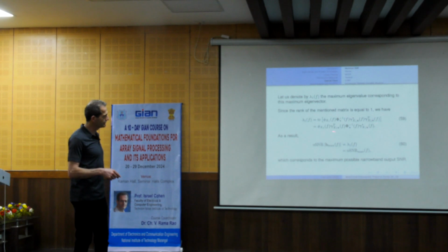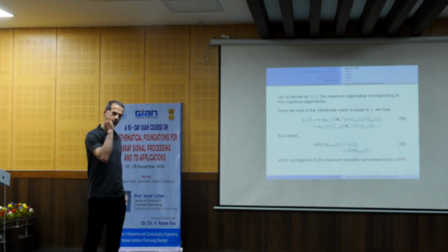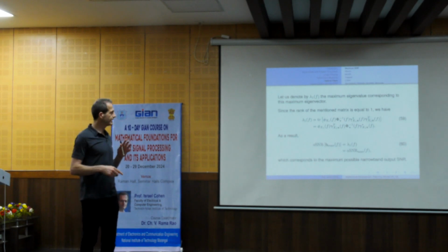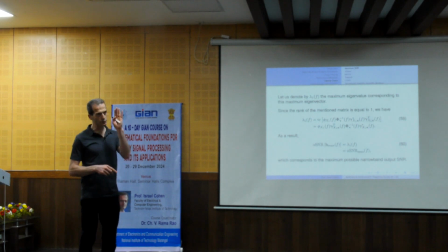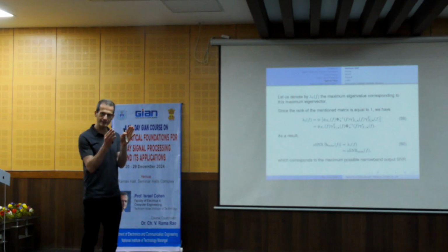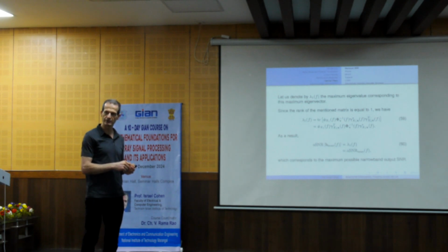This value says that when we steer the observed signal, we look for the desired signal, it comes from this direction, right? So when we look to the direction of the desired source, we see how much noise comes from that direction. You see, so this gives us the amount of noise that comes from looking to the desired source direction.